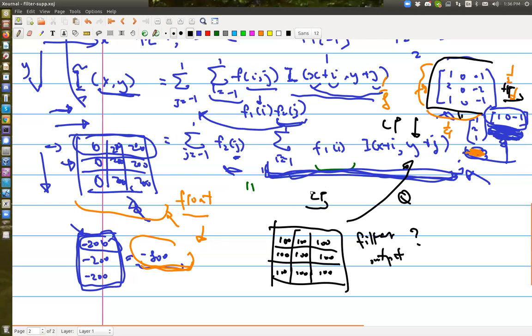Sorry, not low pass. I have low frequency components only on this side, and low frequency on this side as well. So I can get it in this direction, but I cannot get it in this direction because I have high pass on this side. If along the horizontal direction there is only low frequency component, it just cannot pass through the filter. Therefore I will get 0.